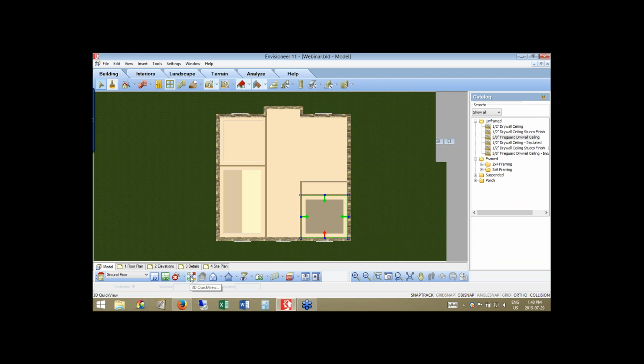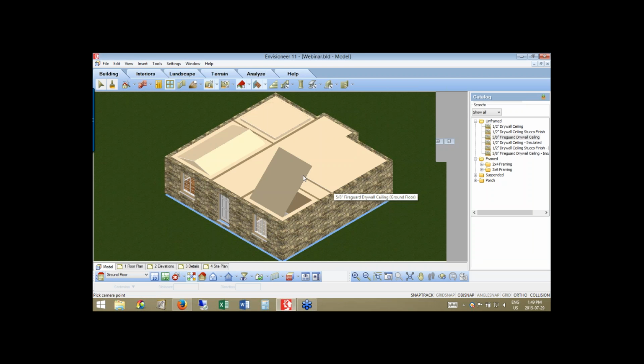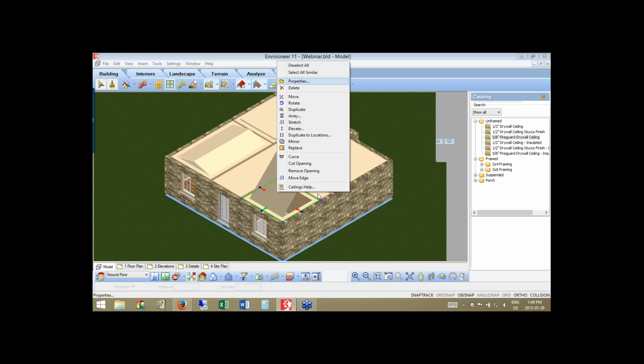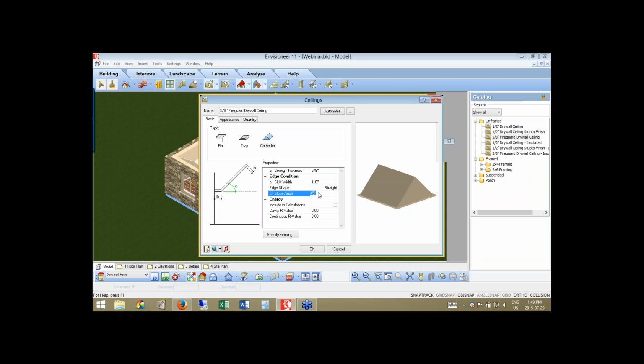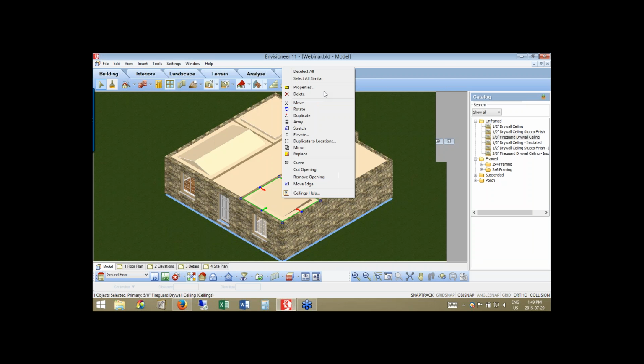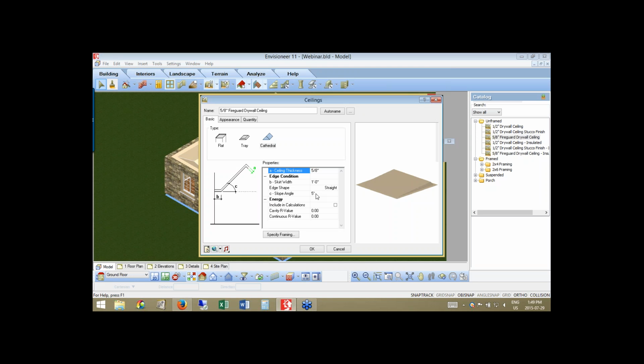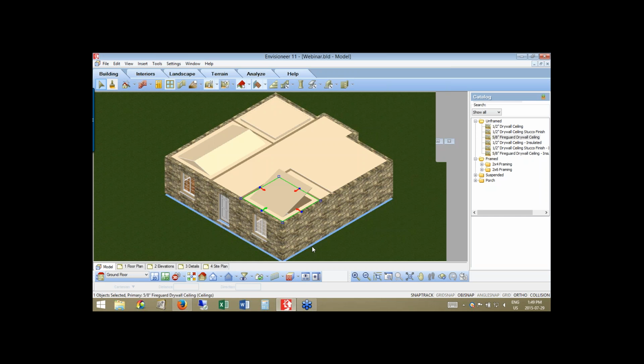So if I go to a general 3D view, I'll pick on this 3D quick view button down here at the bottom of the screen and look at our model from the lower right. We can see the ceiling going up on that 45-degree angle. So I can select it, pick that one green arrow at the very beginning there, look at its properties, and tell it instead of being a 45-degree, let's just make that maybe a 5-degree slope, so it's much smaller. Again, any property that you want. Keep going back, changing them, take a look at your design, switch them around, and you can have all of those different values put in.